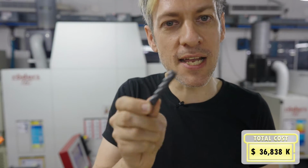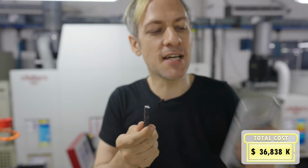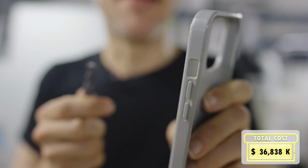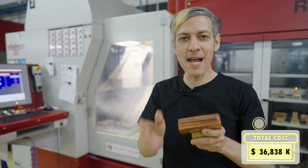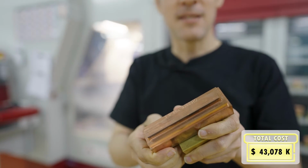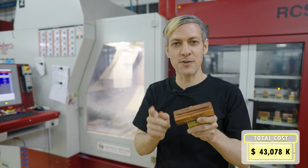All the machines behind me cut metal by rotating a cutting tool, and because of this there's always going to be some radius. But many times on phone cases there's a square or rectangular hole, and the question is, how do you cut a square hole? The way they can cut a square hole is first they cut a copper block, and then later I'll show you how they use the copper block to eat through the metal.